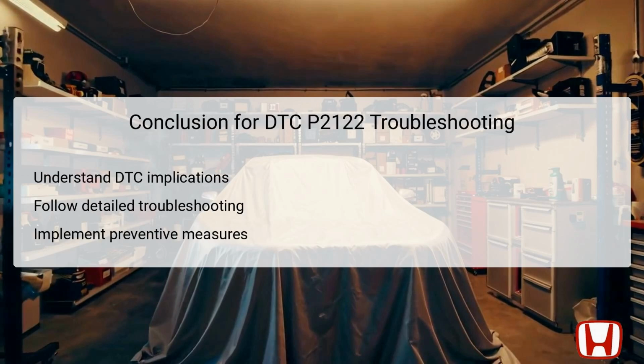In conclusion, understanding DTC P2122 and its implications is vital for maintaining proper vehicle performance in the Honda Pilot models from 2016 to 2022. By following the detailed troubleshooting steps outlined, you can effectively pinpoint the root cause of the APP sensor circuit low voltage issues.